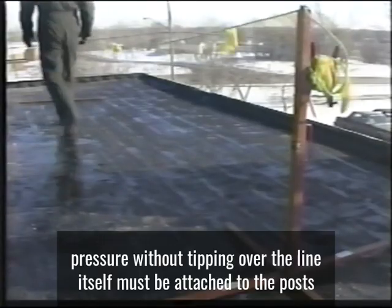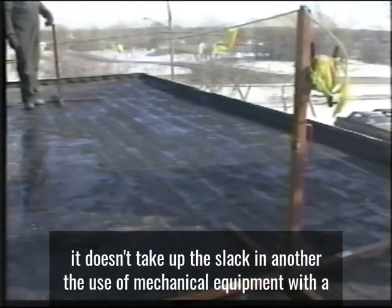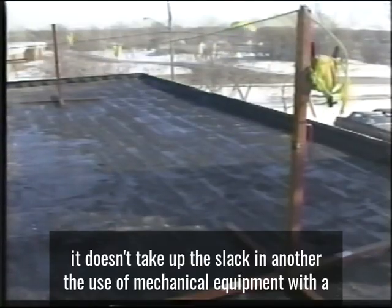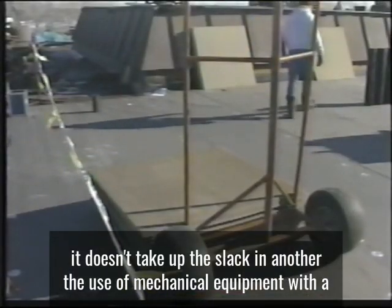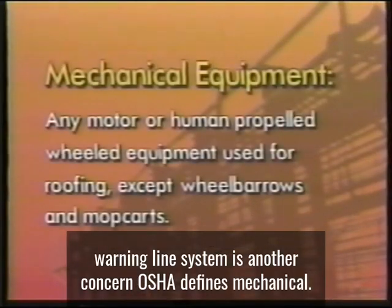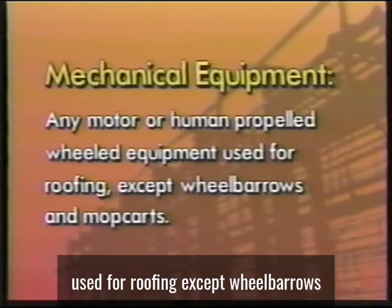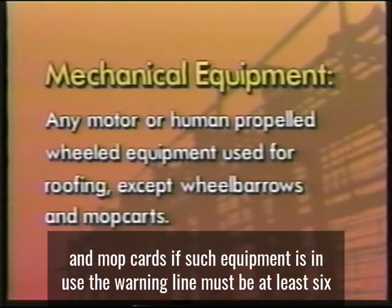The line itself must be attached to the posts so that if it's pulled in one area, it doesn't take up the slack in another. The use of mechanical equipment with a warning line system is another concern. OSHA defines mechanical equipment as any motor or human-propelled wheeled equipment used for roofing, except wheelbarrows and mop carts.